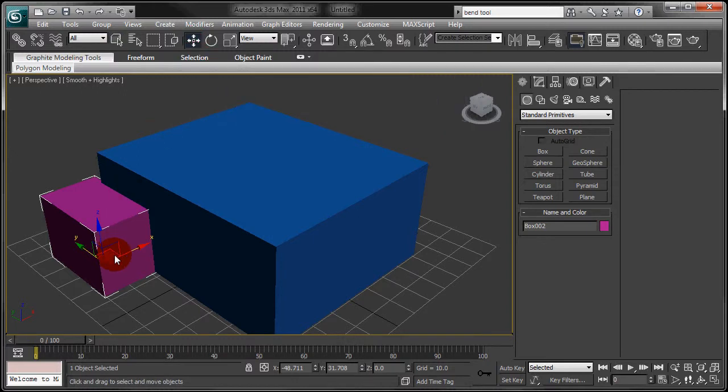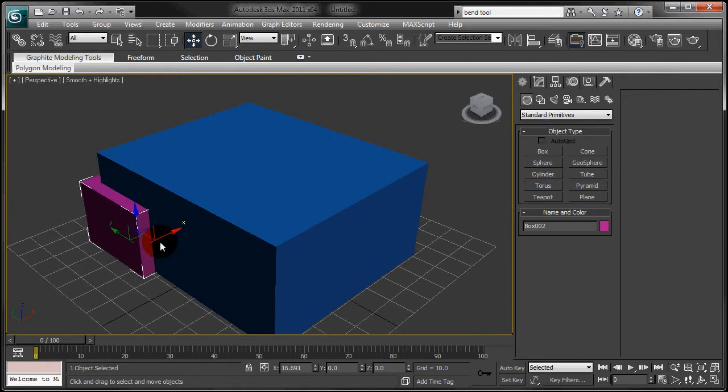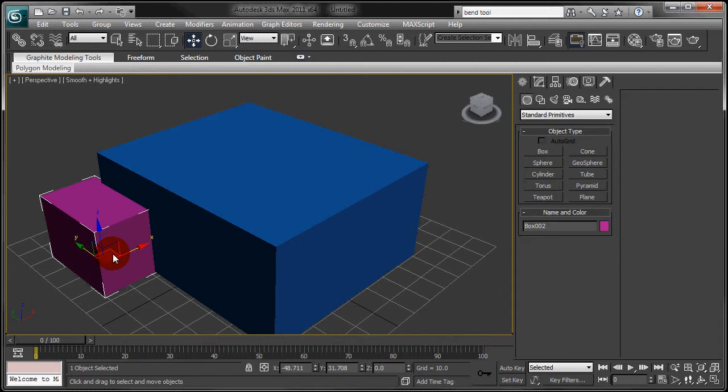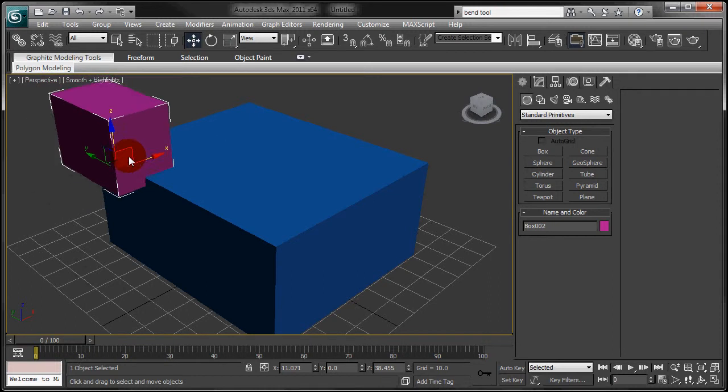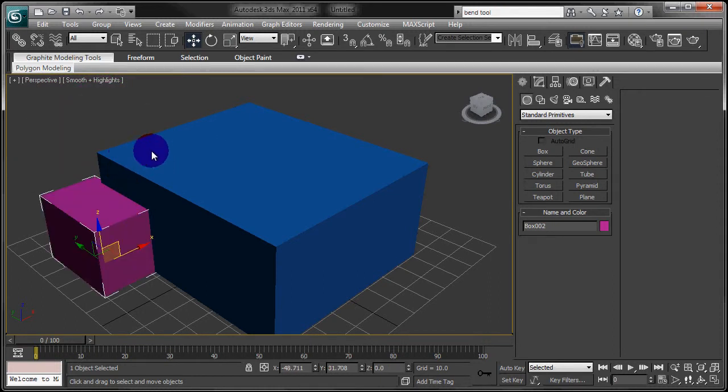Drawn in front of the object is what is known as the gizmo. The gizmo is a visual helper that allows you to move the object in any particular direction or all. Different parts of the gizmo will move the object in different directions. We can constrain the movement to a single axis, such as the x-axis, or to only 2 out of the 3 to make it move along a plane, such as the floor, or say along a wall. If you want more precise measurements, you can right-click on almost any tool and get more accurate translation parameters.